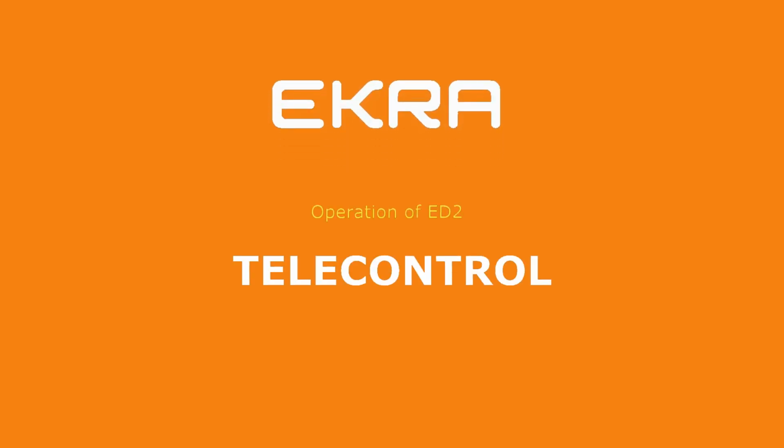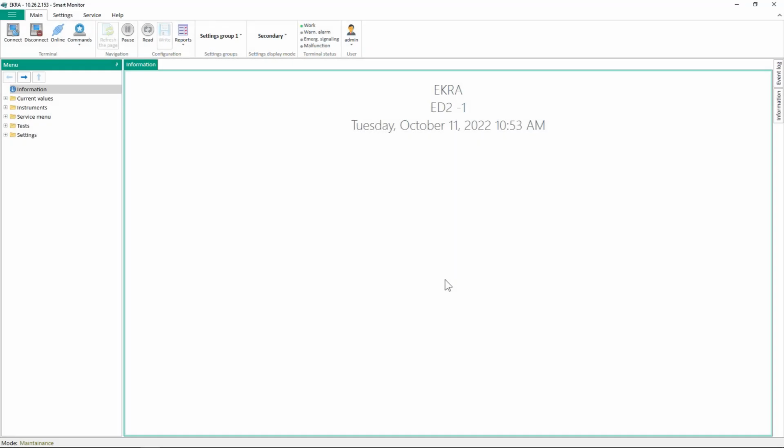In this video tutorial, you will learn how the telecontrol of operation modes of functions, setting groups and switching devices is carried out in ED2 devices. Operation modes of functions and setting groups, when controlled locally, can be changed in one of two ways: through binary inputs or using electronic switches.